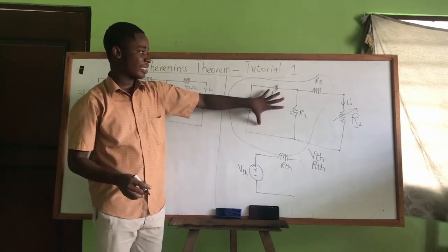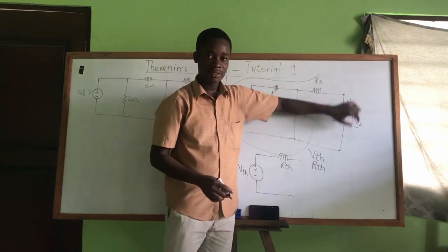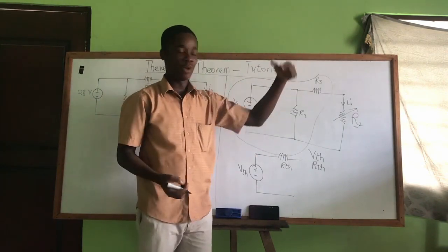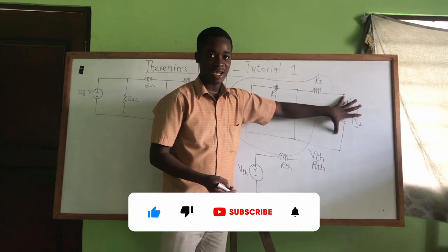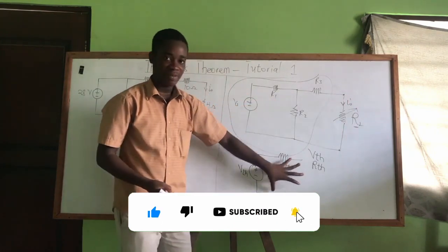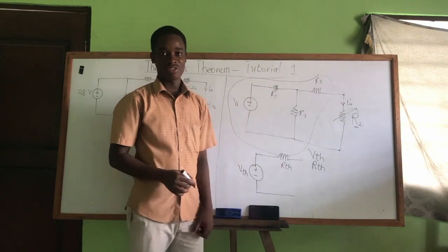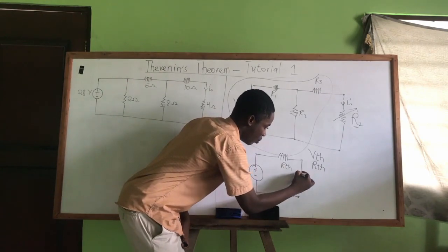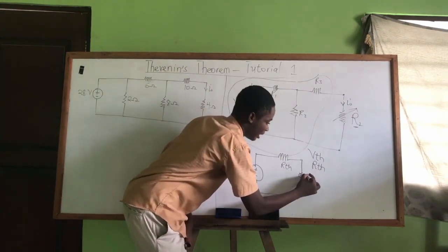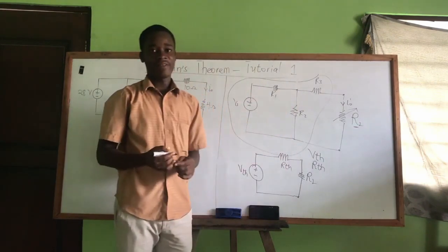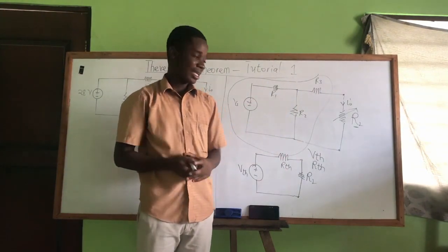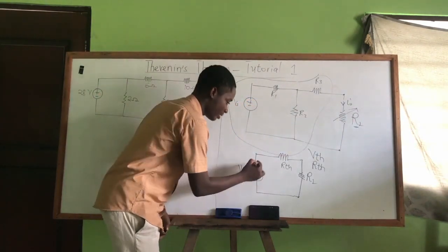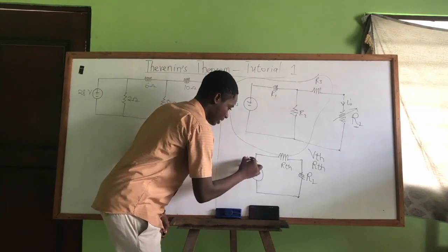Now we realize that in this circuit, we've connected a load to the terminals. So after getting its Thevenin's equivalent, we can bring back our load, the load that we removed and didn't consider. We connect that load to the Thevenin's equivalent circuit and calculate the current through that load using this equivalent circuit. That current will be produced by the source, which is I.